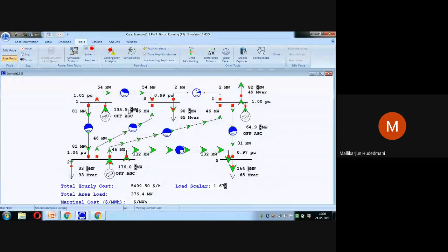the reference bus, because this is software. This software has to simulate and show the responses or impacts of that. Hence, that is done only by the swing bus. Even though I turned it off, the swing bus is the only bus the software compels to respond and balance the load, so that is how the impact of the change in load is addressed whenever AGC is off.